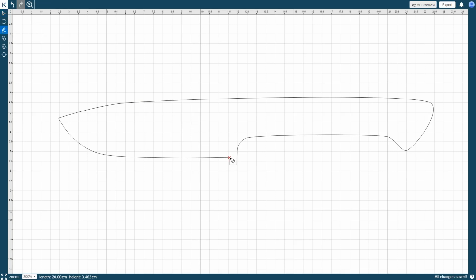For the bolster, activate the Bezier tool, left-click where the finger guard meets the blade and drag upwards towards the spine, and then double-click to complete the path. For the bevel path, start at the knife point, drag right to your desired length, click and then finish down at the knife edge, double-clicking again to finish the path.